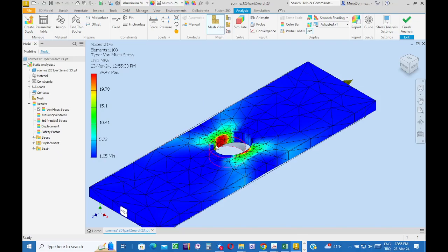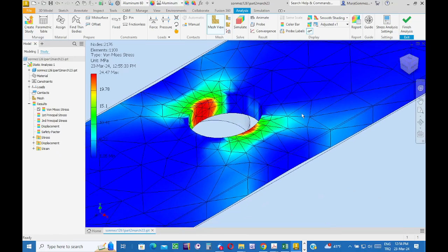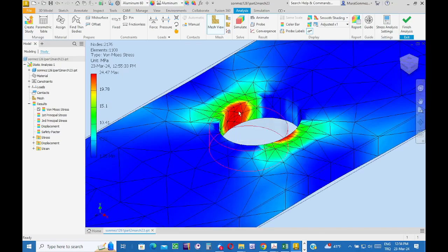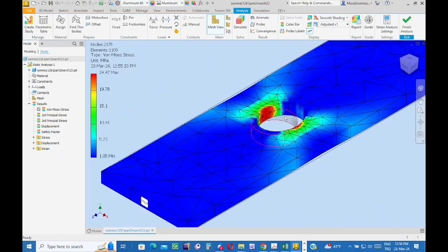It is important, since we said to repeat the calculation each time decreasing the mesh size, you see Inventor, at the places only where the stress is maximum or 75% or greater, decreased the mesh size. You see here in the vicinity of these parts we have smaller finite elements. The rest are coarse elements, bigger size. Yes, Inventor did it automatically.